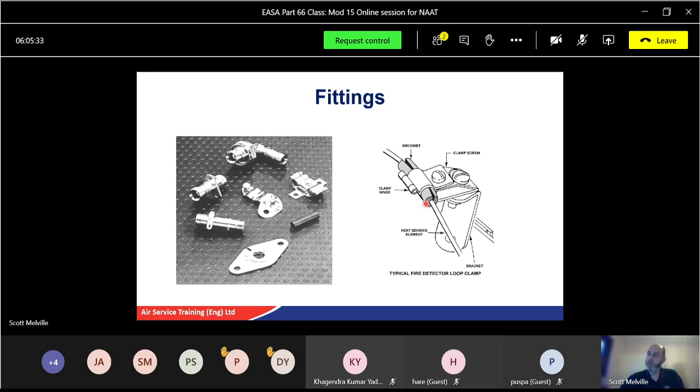These grommets, these rubber type grommets, they can be black, they can be red. They do wear out through time, so make sure you actually look after these. Inspect them with a good torch. The cam locks can vibrate open, so sometimes the little cam lock key can open and then the hinge opens out. So again, make sure they are secure.